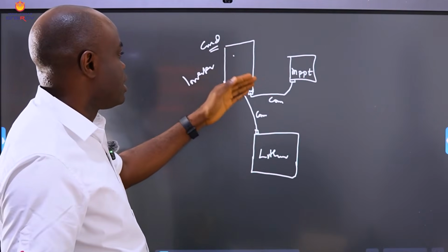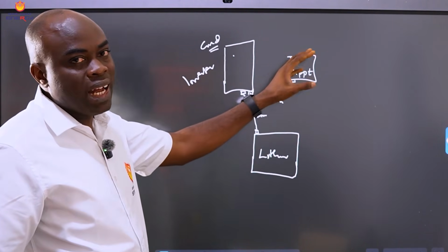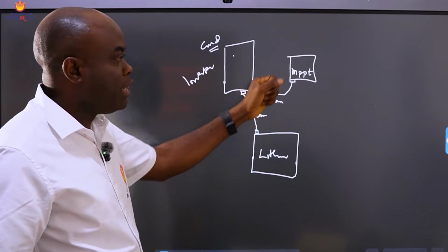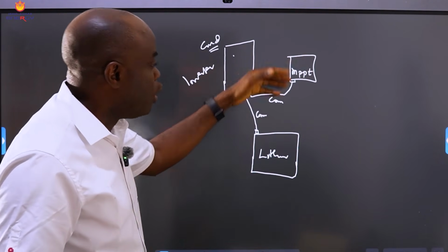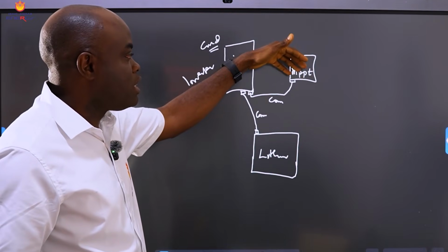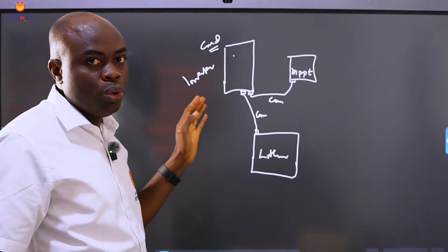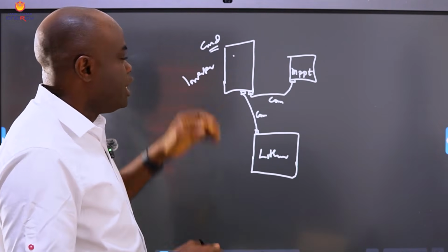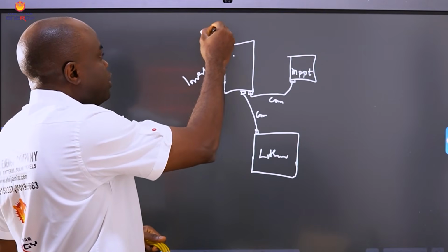What it does is, because of this communication, it will monitor that there's a lot of power from the panel. It pulls that power from the charge controller, or it allows the charge controller to charge your battery and also give power to your load. So your grid is being maintained, like there's no usage from your grid. 0 watt is being consumed.